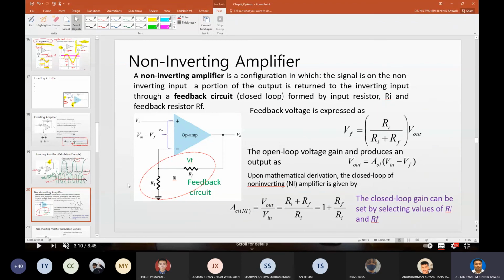However, if you don't like the inverting effect because now the signal is inverted, you can use a non-inverting amplifier. Okay. In this case, the input will come through the non-inverting input, for example, from your sensor. The input signal may be from the sensor, and in this case, now the inverting input will be grounded, however with some portion as well through the one called the feedback resistor.